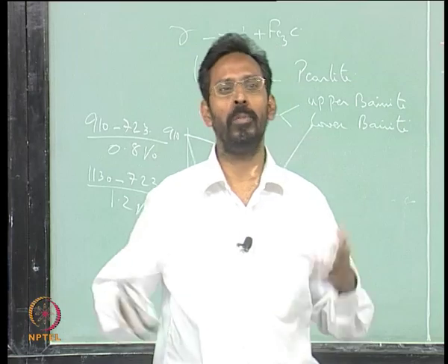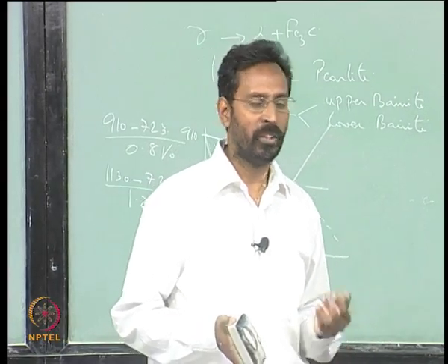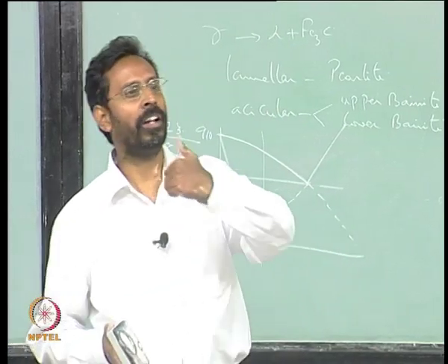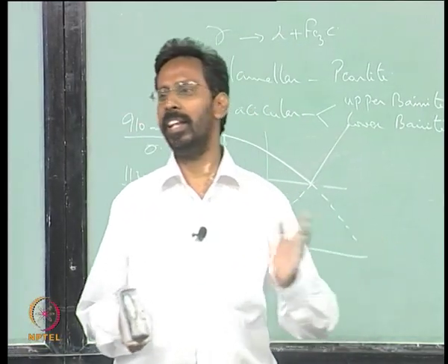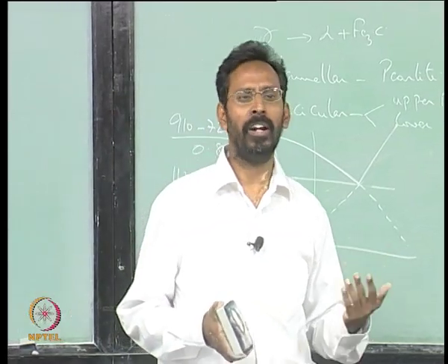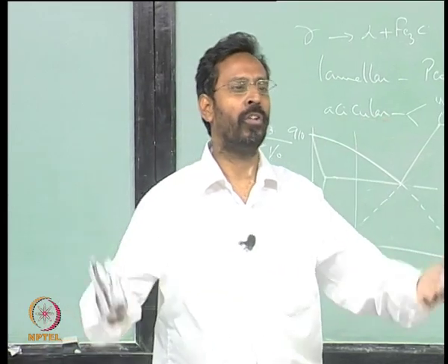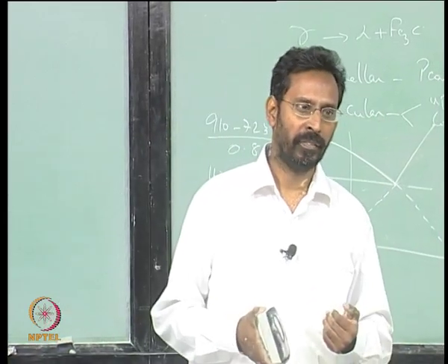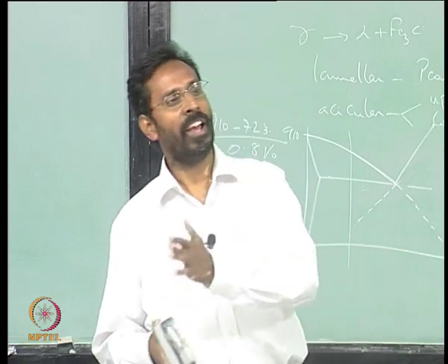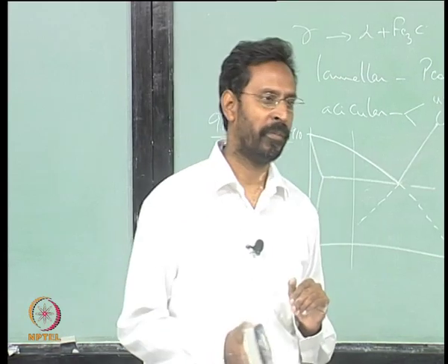It is like having too many dislocations, you have work hardening taking place. So similarly here, any alloy diffusion or chemical diffusion, not self diffusion, chemical diffusion is going to be more difficult if the solute content is higher. That is why chemical diffusivity, if you read about diffusion, is always a function of composition.